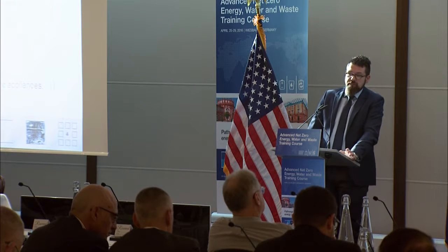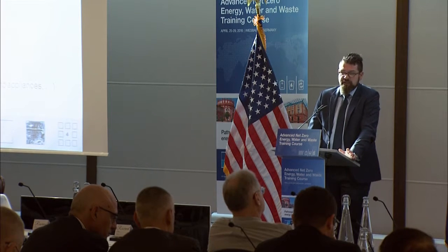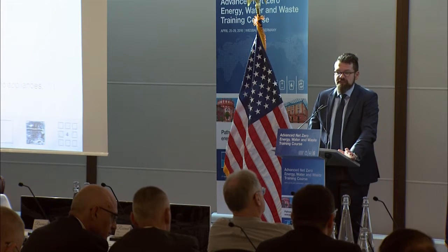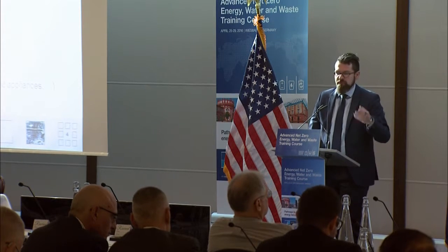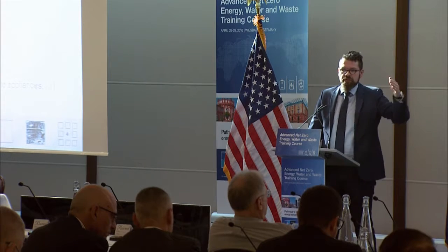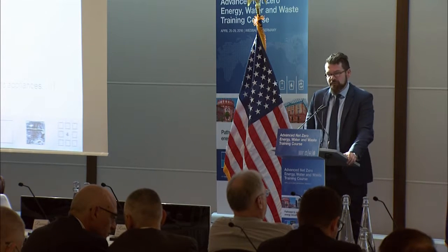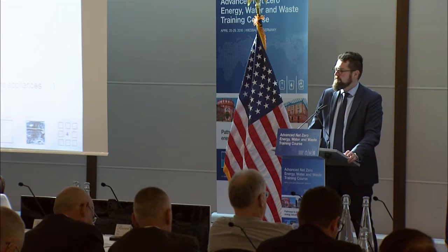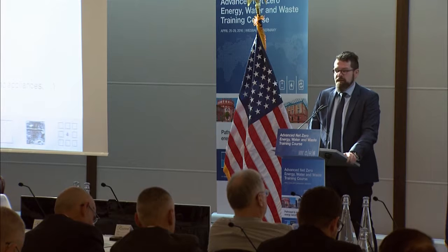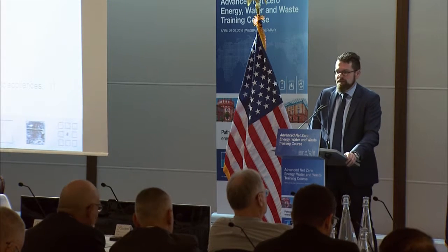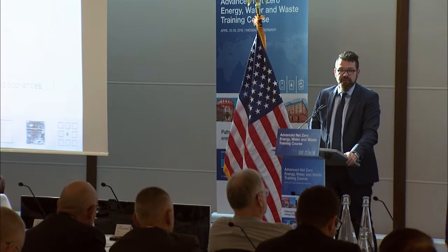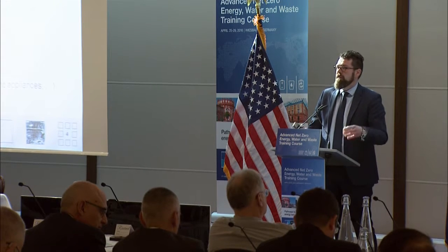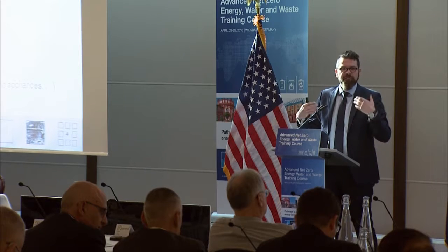Other most important impacts are the size of the buildings and the building physics, meaning what the external losses are through insulation, the wall to the outside, and the windows and such. Then we have internal heating sources. So here are some computers inside, we have electric lighting and other electric applications, and everybody of you radiates some kind of heat into the room.